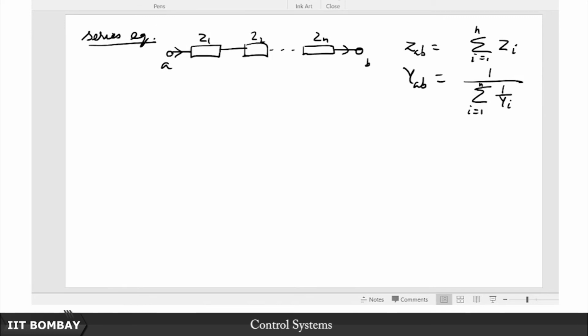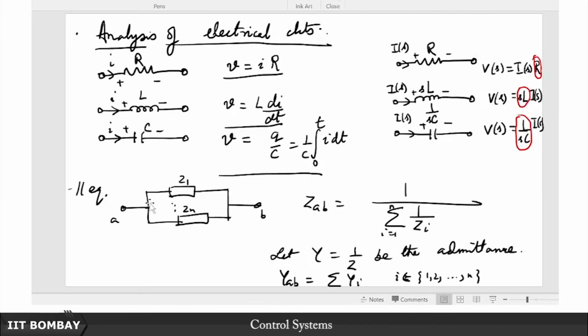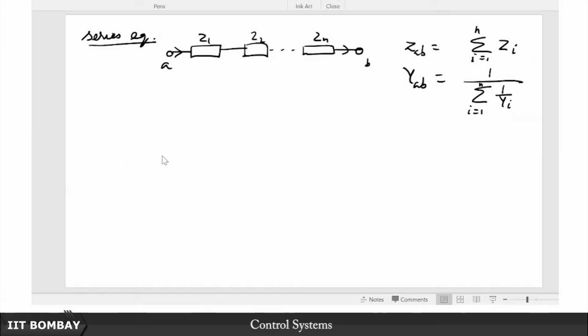So next we bring ourselves to the fundamental question of when do we use Kirchhoff's voltage law and when do we use Kirchhoff's current law. Now suppose you are just given pure series or parallel circuits, you do not really always want to go into the Kirchhoff's voltage law and current law and make those loops or nodes, right. You can always reduce it to an equivalent series circuit or an equivalent parallel circuit.